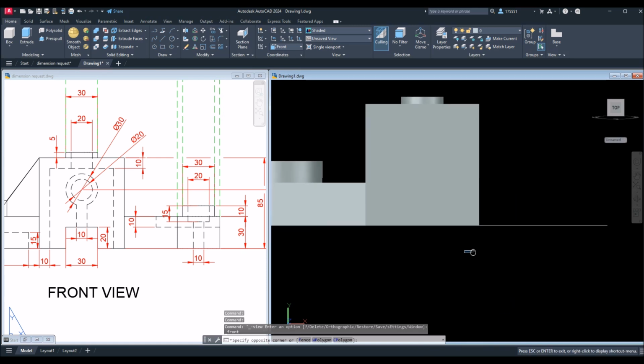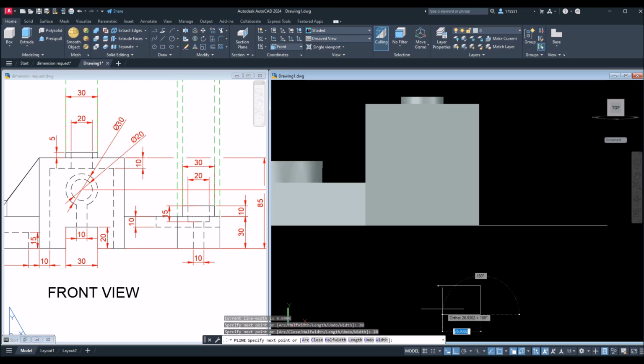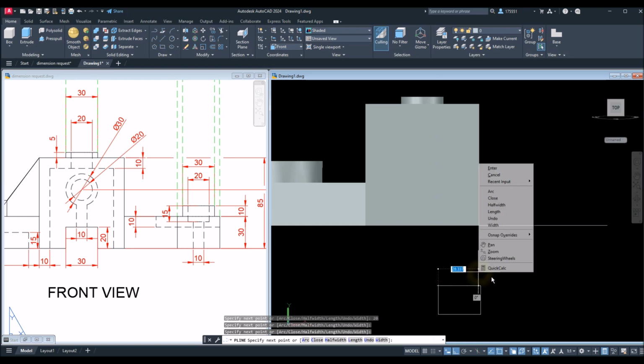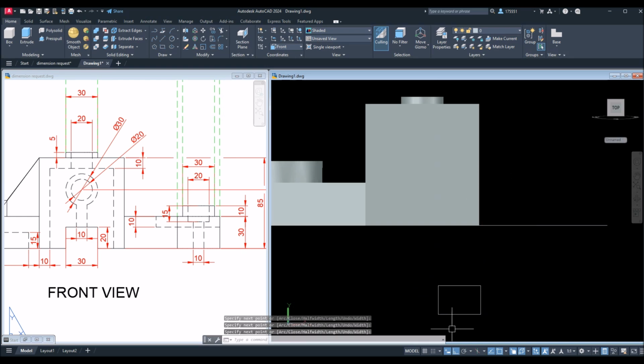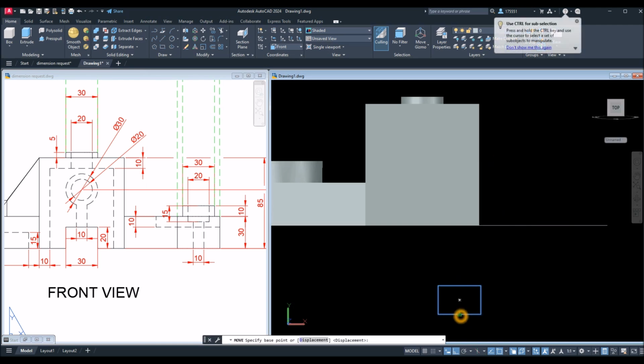and I'm just gonna draw a rectangle separately. So this one here is 30, go downward for 20, another one for 30. I'm just gonna track and then click that in point. Since I use this one, polyline, it's now one object, so move from midpoint to midpoint.